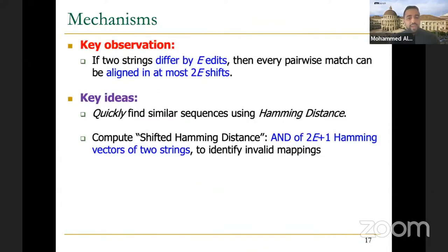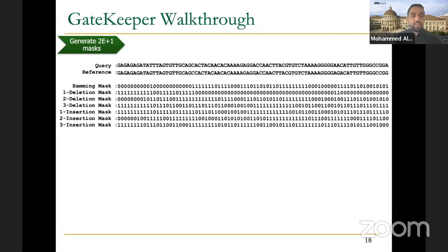All right, so that is the algorithm. And now for the implementation, or how we really implement it on FPGA or on logic gates. So first, let's see a real example with real data. This is a real sequence from the human genome. What we need to do is the Hamming distance calculation, just XOR between the 2 sequences. Let me annotate it. We do first the Hamming distance calculation, just XOR between them, right? And you can see it's 0 where they exactly match, 1 where they don't match in the corresponding locations.